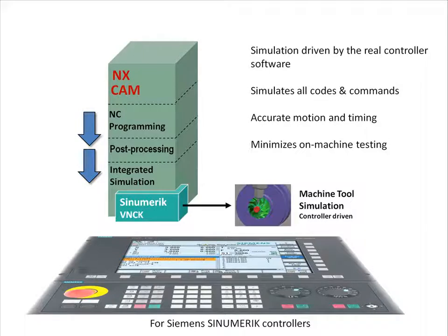This option for Siemens-controlled machines is available as an add-on to NX-CAM. It is called the VNCK option, referring to the name of the controller core software, the Virtual Numerical Control Kernel.